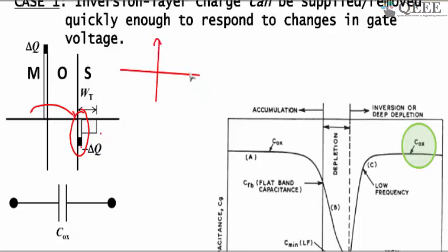If this is Vg and this is psi s, we saw that the psi s may increase and finally it gets pinned at accumulation and inversion. So this is what happens here, your surface voltage gets pinned, that means there is not much change in the voltage. Any small change in the surface voltage can create a large number of electrons, so practically there is no modulation of the surface voltage.